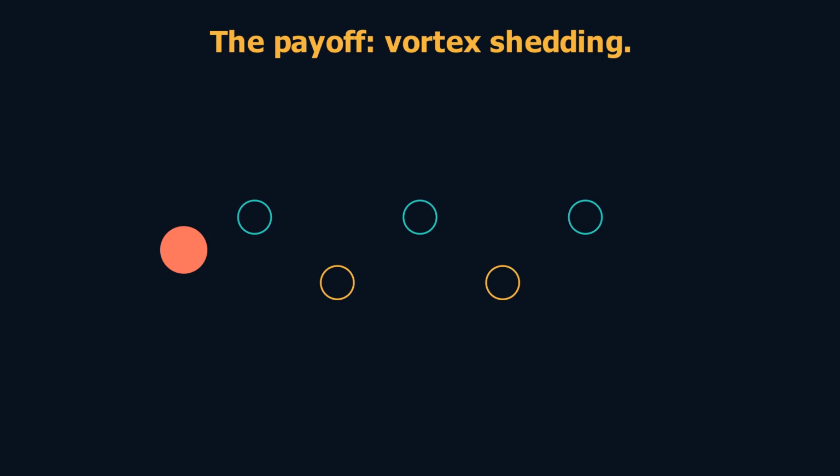This is inherently unsteady, so you'd solve it with pimpleFoam from episode 9, and likely a turbulence model from episode 10. Everything we've built comes together in this one iconic flow. And it's not just pretty: the shedding frequency is a real, measurable engineering number, captured by the Strouhal number. Get it wrong on a bridge or a chimney, and resonance can destroy the structure.